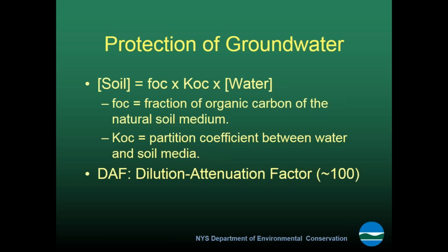As we're looking at developing a protection of groundwater number for the perfluorinated compounds, it's becoming increasingly clear that that number of 100 is not going to be appropriate for use in this situation, for two reasons. One is that those chemicals do not degrade in the environment. They are remarkably persistent, and they don't degrade from either chemical actions or biological activity.